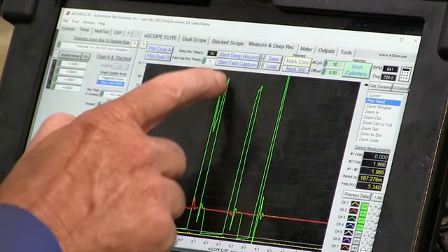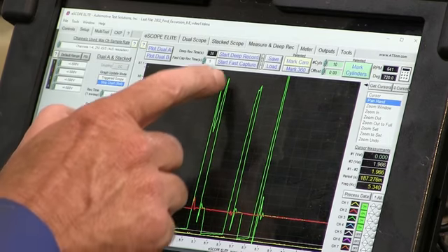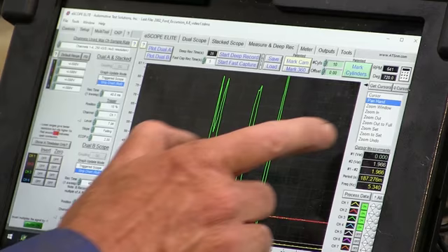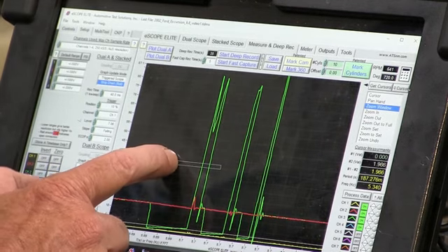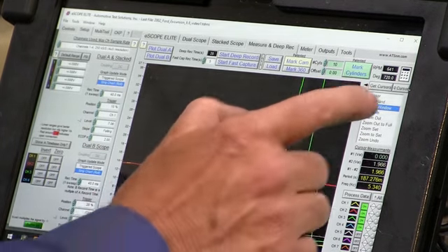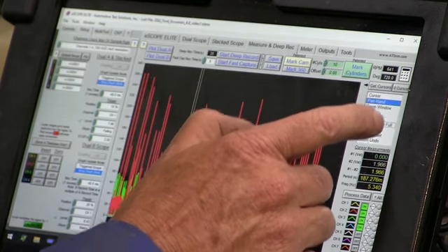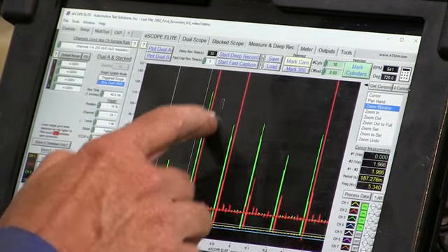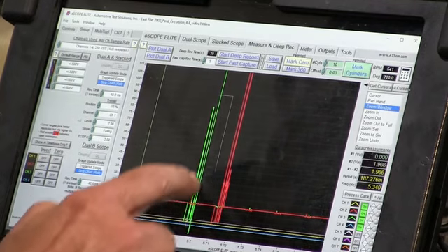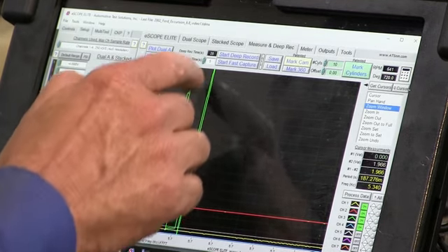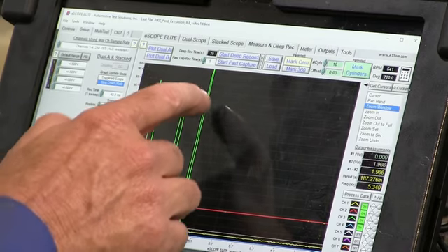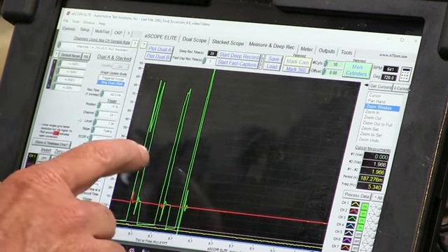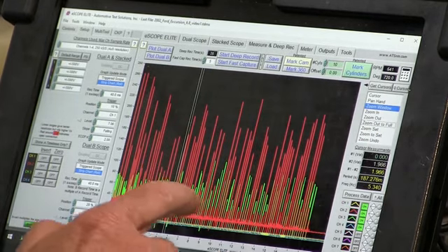Okay guys, do you see how this is kicking up? That looks lean right away. That cylinder looks lean. You can see it's got a kick up. But normally when I got multi-strike, the one I want to look at is at the end. It's the last one. And you see how we just came way up? We didn't even get a burn. There's no plasma. That plasma, it looks lean. But let's just look at a couple of these and try to figure out what's going on.